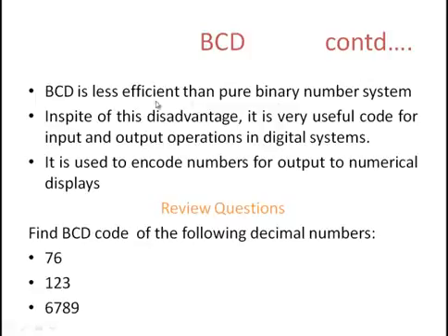BCD is less efficient than the pure binary system because in BCD more bits are used to encode a decimal number than pure binary code. But in spite of this disadvantage, it is a very useful code and is used to encode numbers for output to numerical displays like LCD. This was all about BCD. Some review questions are given here which you may practice in order to understand BCD in a better way.